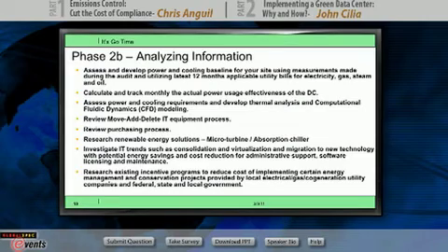One way is to use a microturbine, for example, where you can actually generate energy at your site, while you can use the energy wasted from your microturbine, the heat that the system generates, and use that to generate, for example, chilled water through an absorption chiller, or to heat some hot water throughout your site.